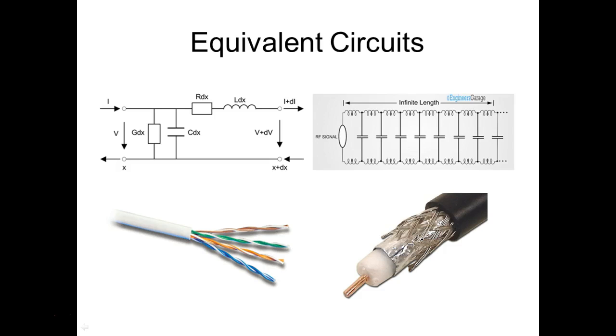You understand? Depending on the number of twists you have per inch, these act like a little capacitor, and these act like little inductors. So this we call twisted pair cables, and this sets the what? The impedance of the cable. This is 100 ohm. I think it's at 10 megahertz. I'm not sure. I have to go back and look. So when you're splicing this stuff and terminating, you can't untwist it a certain length, because if you untwist it too far, you screw with the impedance of the cable.